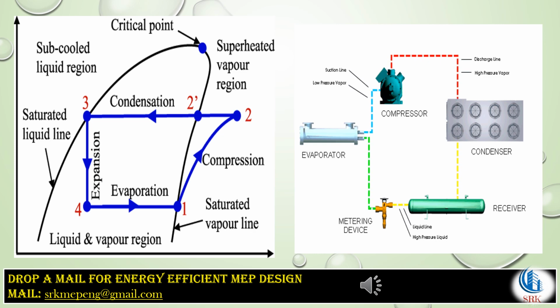The struggle for engineers and consultants is to minimize the compressor lift, the power absorbed by the compressor or chiller, to provide a certain amount of cooling capacity. This involves employing various design strategies, especially in modern design philosophies.